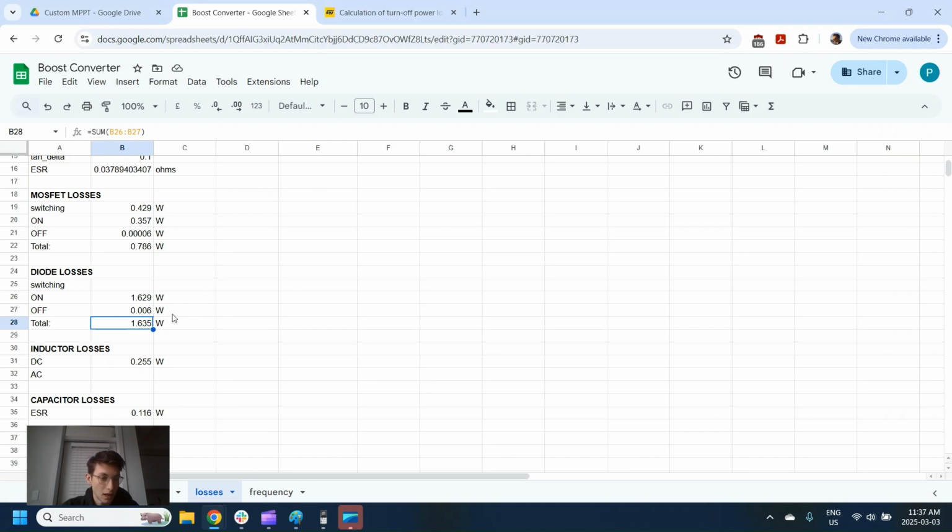And we can look at that as basically the voltage that it's blocking times our leakage current, which we can just get from the diode itself. That's going to be on our on cycle, so 40% of the time. That gives us these losses here. A similar thing, we're separating into two different sections where we have the on time and the off time, but it's just going to be inverted in this case because the diode is complemented to the MOSFET.